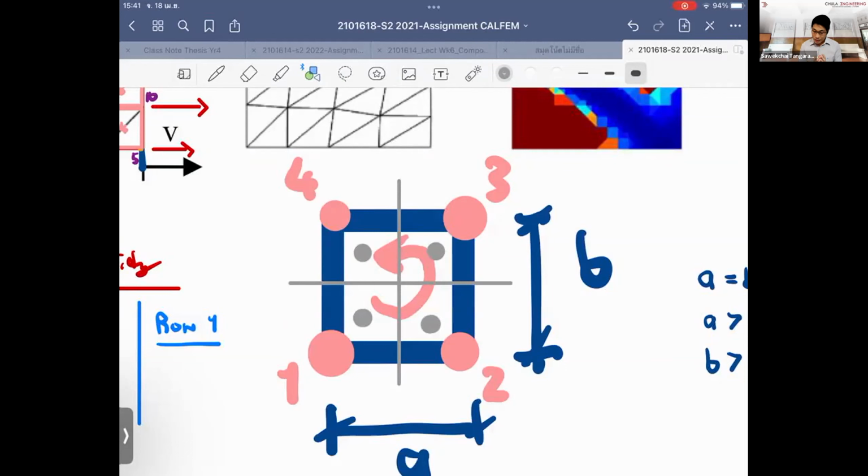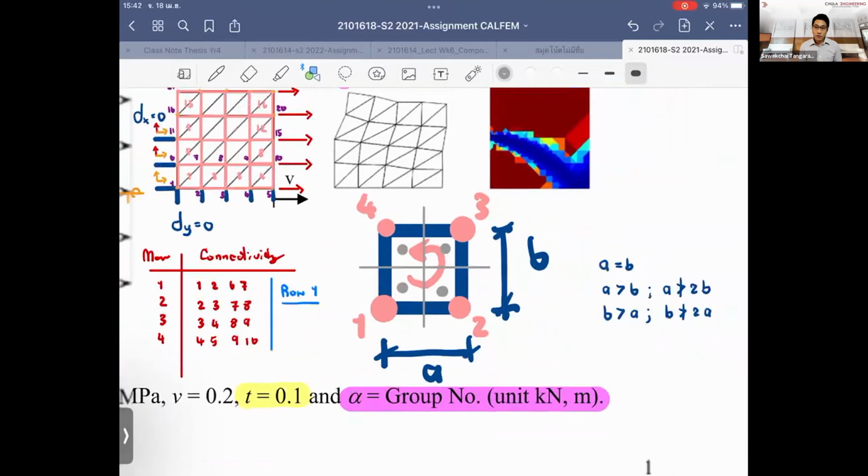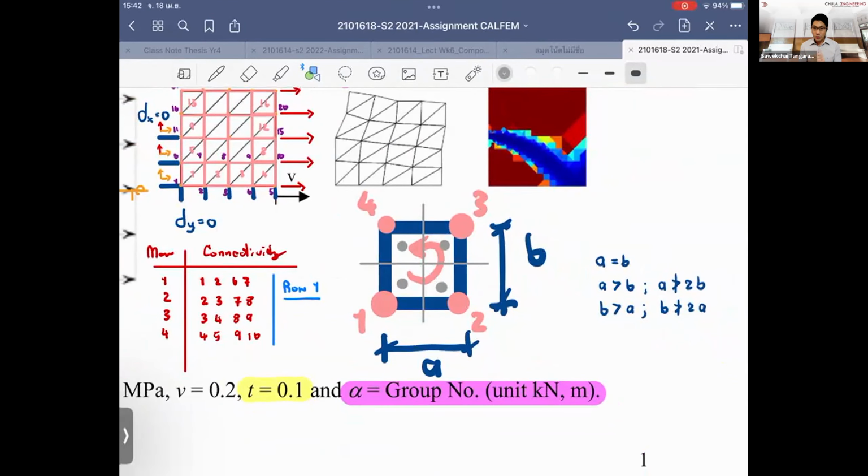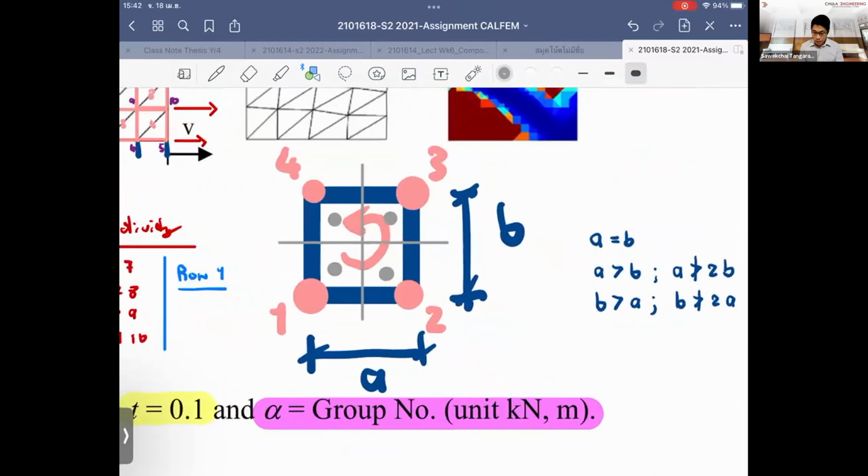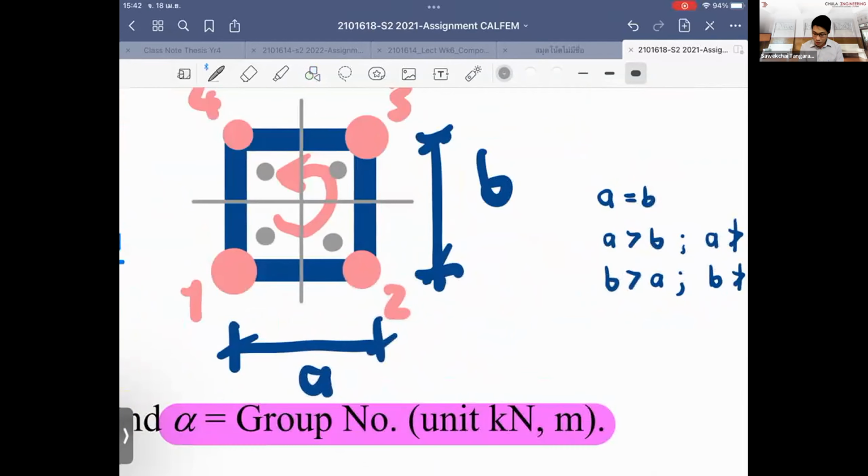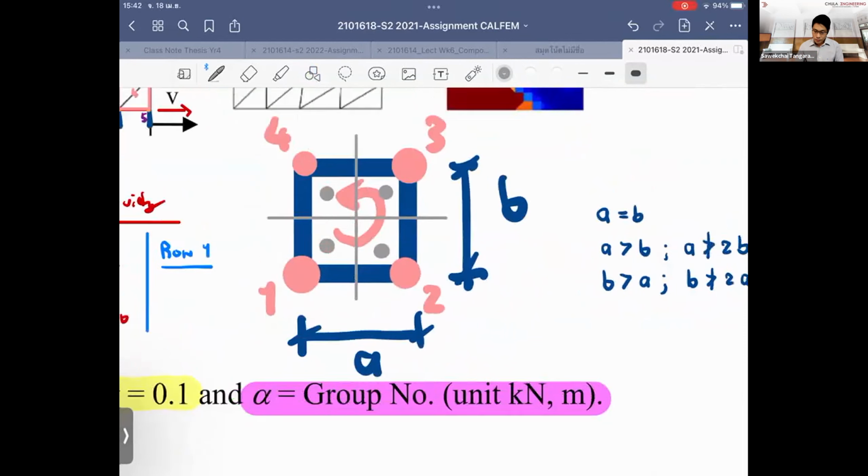You already learned what the Gauss points mean, which is we use them to approximate the integration. Because when we form the finite element formulation, we have to use integration, and we cannot have closed form integration, so that's why we use the integration rules, which is the approximation, and we use a Gauss quadrature. Quadrature means 4-point integration rules, right?